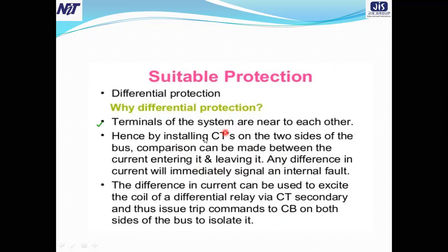So using the property of differential protection, we can identify the problem with the help of the immediate signal, because we know that if there is any difference in the current, it will immediately signal an internal fault. Now, number two is completed.